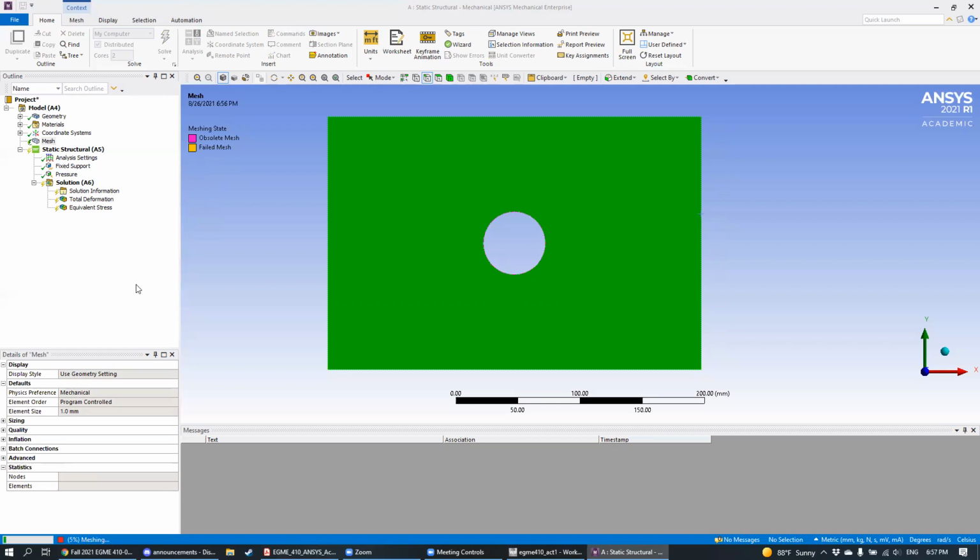So it's still meshing. Yeah, I was just realizing that we meshed with something just over 1,000 elements, so nothing that crazy. Actually, I think what people generally expect is that if you have an element size of, let's say, 10, and you cut that in half, you'll have twice as many elements. But it's actually a quadratic relationship.